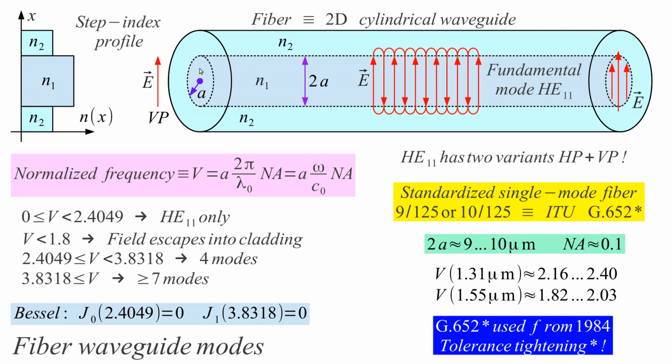So 1 part out of 1,000 of the power. So from a 10 milliwatt LED, we can at best get 10 microwatts of guided power inside our fiber. So this discrepancy between LED and single mode fiber didn't go together.